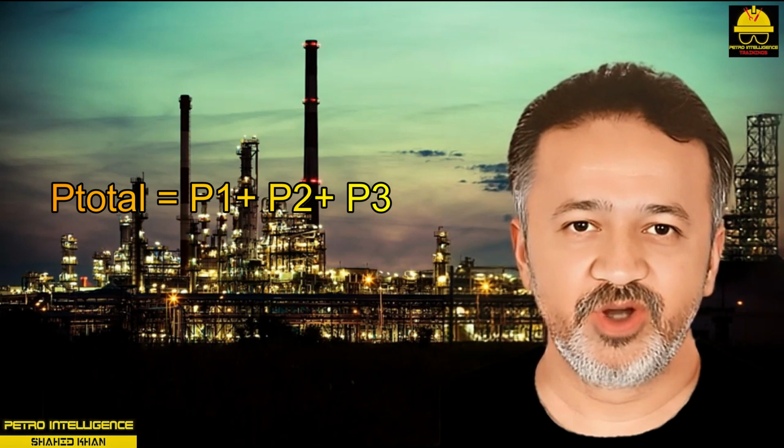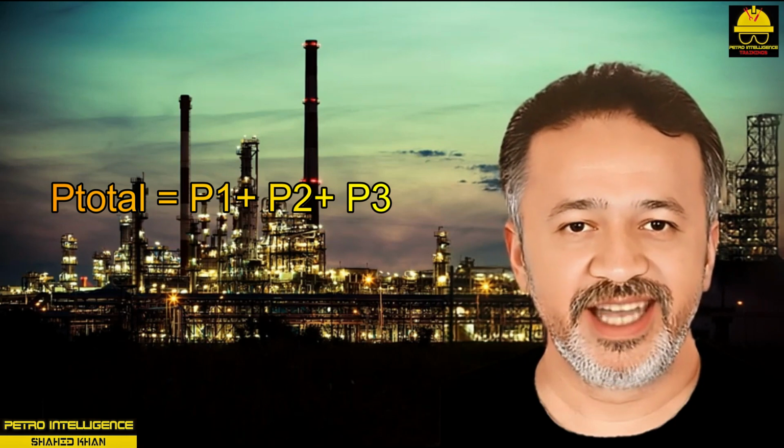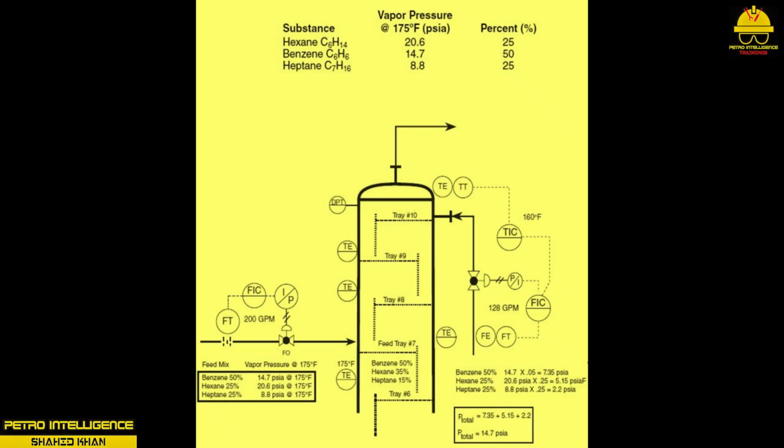The different trays in the column have unique molecular components associated with volatility. If you know the vapor pressure exerted by a specific chemical, you can calculate its partial pressure on the various trays. To do this, we use Dalton's law of partial pressure, that is P total equals P1 plus P2 plus P3, which states that the total pressure of a gas mixture is the sum of the pressures of the individual gases, that is, the partial pressures. This picture illustrates Dalton's law of partial pressures.